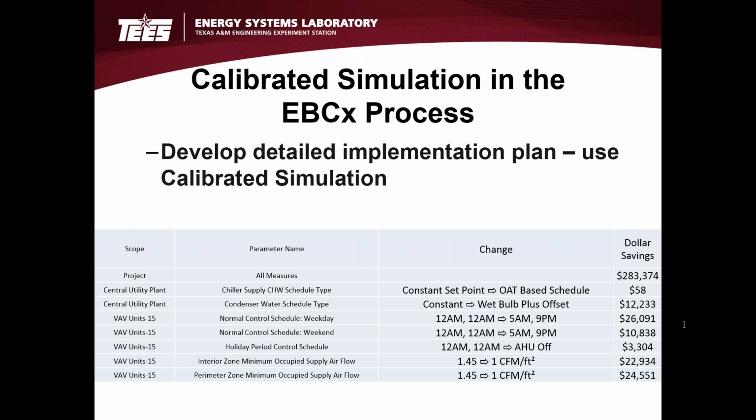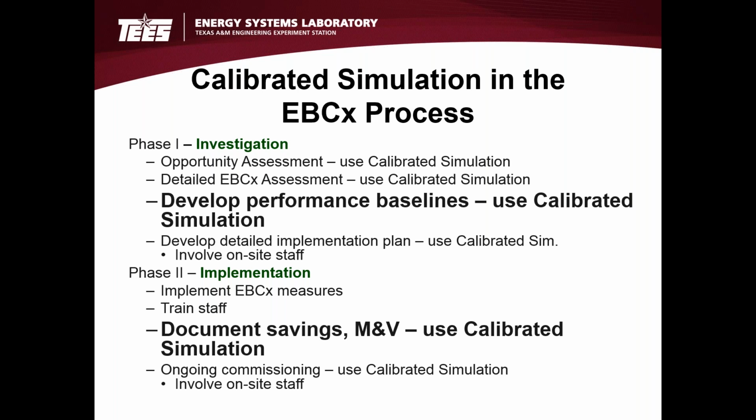We certainly want to do it at a late stage, and in this particular case, changing the chilled water supply temperature appears that it would have a negligible savings, and hence this helps the engineers decide where they're going to put their time and effort in implementing measures. Because you may sometimes have a measure that will take a lot of implementation time and not provide nearly as much savings as some other measure that will possibly provide even more savings.